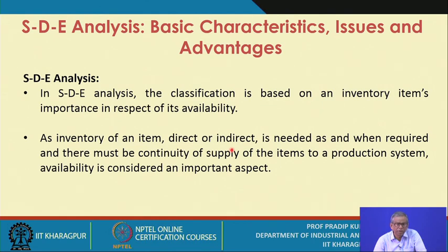The criticality depends on its functional value in relation to the concerned products or the end items. So, while you carry out VED analysis, you must have a thorough understanding of the design of the product, particularly the main components or sub-assemblies, the functions of which determine the functional value of the product.